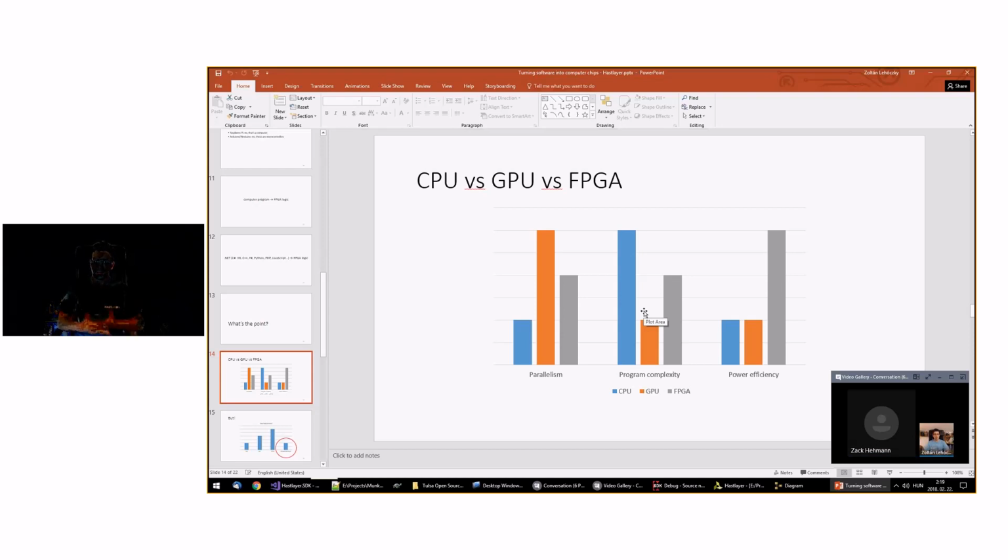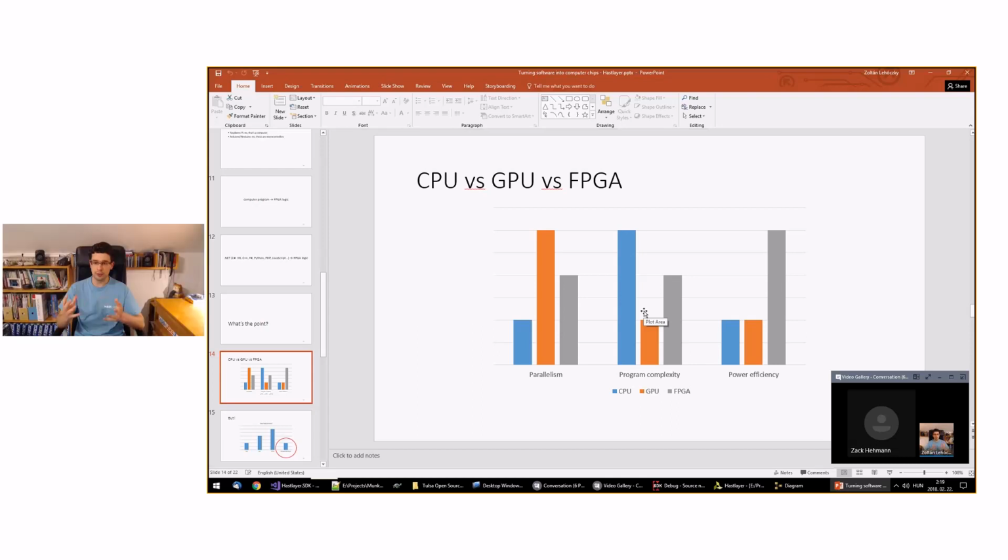So basically hardwired chips, hardwired hardware, and not dynamically reconfigurable like FPGAs. They have the benefit that they can be even more power efficient than FPGAs. They can have denser logic, so more logic per area, so they can have a higher degree of parallelism.